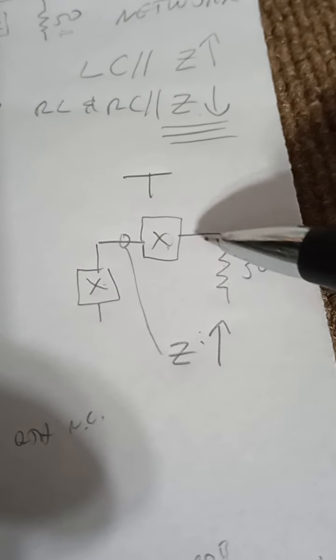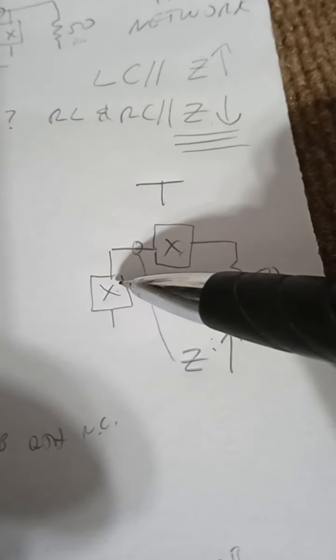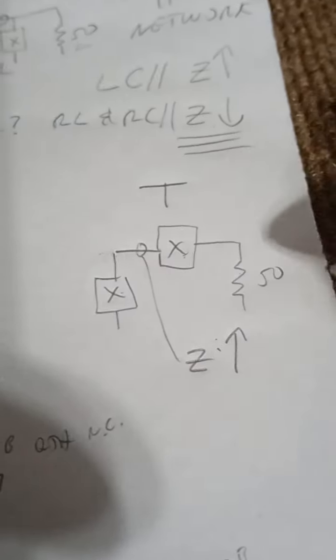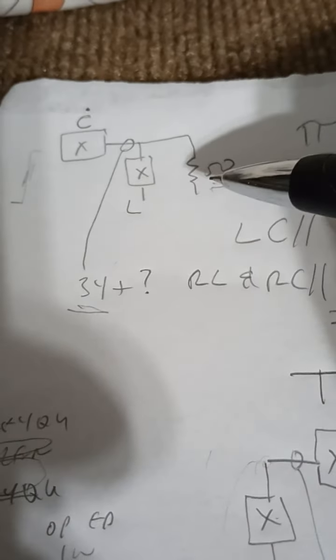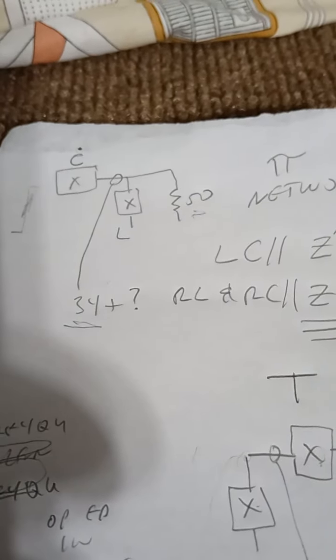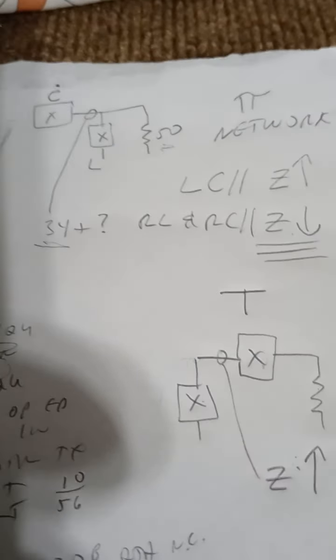So from here, every step over here is a step up in impedance. Then this goes over to a reactance that cancels, so to speak, the residual reactance in this node. Here, there's an immediate step down in impedance, which is not what we want. Nullify some reactance. And then the step up is over here at the input. That's not the correct topology, and for that very reason.